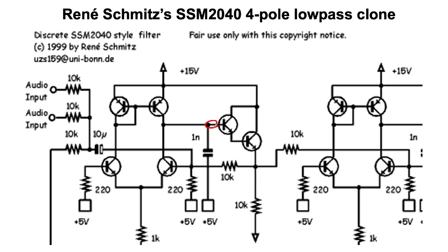So the voltage that's formed here from the current output of this primitive OTA going down through this 1 nanofarad cap, the voltage that's produced by that is being buffered by this structure and reproduced here. And then that buffered voltage is what is being locally fed back here through that 10K resistor.